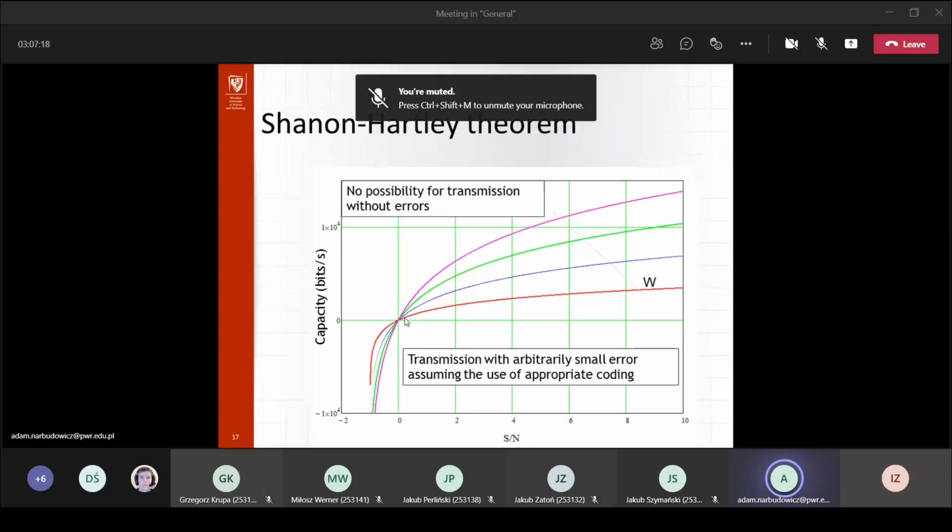I think in practice this is now very rarely used, but back in around 2000, there was a very promising idea of using what was called ultra-wideband communication, right? And the idea was to allocate a spectrum from 3 to, I believe, 12 gigahertz. So basically 9 gigahertz of bandwidth, which would allow communication of very weak signals, below the noise level.